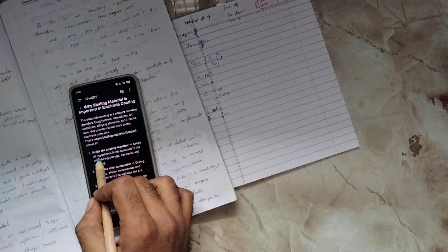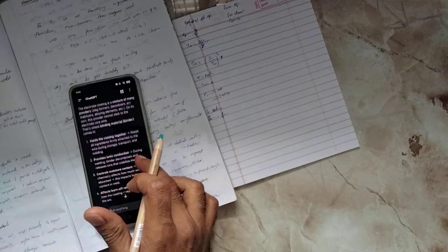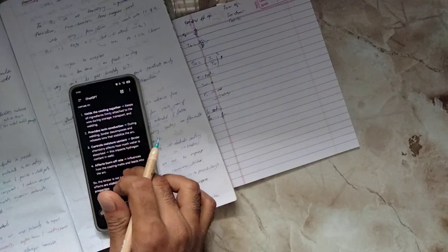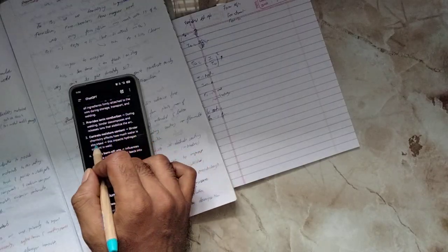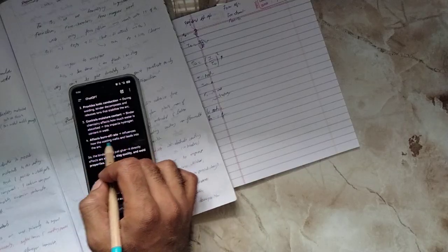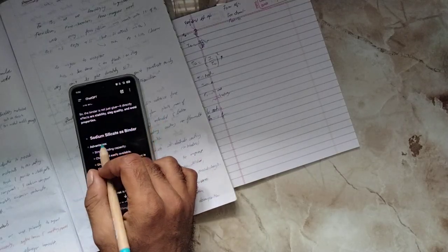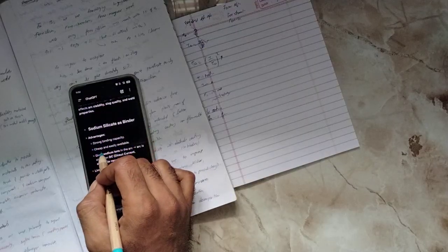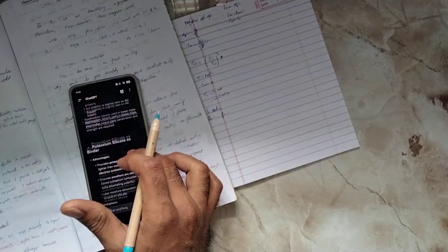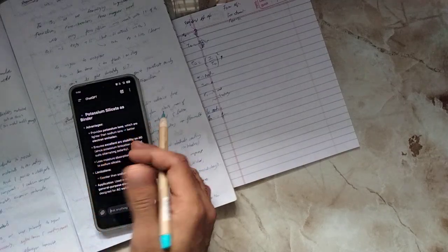That's why the binder holds the coating together, keeps it all in a frame, and provides ionic conduction. During welding, the binder decomposes and releases ions that stabilize the arc and control moisture content. Binder chemistry also affects how water is absorbed, influences how the coating melts and feeds into the arc. Sodium silicate is a strong binder and cheap, with sodium ions, but DC only. Potassium silicate, with potassium ions, is better. Is it okay?